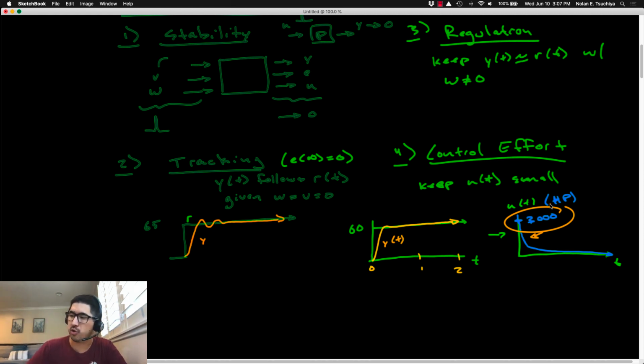Okay, so the idea of control effort is basically just a balancing control objective. It's sort of a sanity check on the other three objectives. Right, so it's easy to get carried away with control design and say, "Wow, this is a fantastic controller." If you look at this control objective with the control effort, you might find that, oh, well, if I wanted to implement this controller, it would be impossible to do. Okay, so this is the fourth control objective, and what we're going to find later is that this control objective, the fourth control objective, kind of fights against the other three. So it basically becomes this balancing act of, well, how do you determine what's the best for your application?